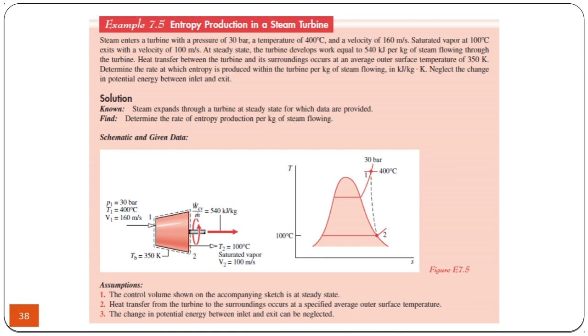Normally, in the calculations, we most of the time assume that the steam turbine is isentropic, meaning that it's a reversible turbine. If it was a reversible turbine, then we would have a situation at which S1 would be equal to S2s, which is isentropic. But because of the irreversibilities, you see that there's an increase in entropy, and this amount of increase in entropy is actually the entropy that's produced inside the turbine because of the irreversibilities.